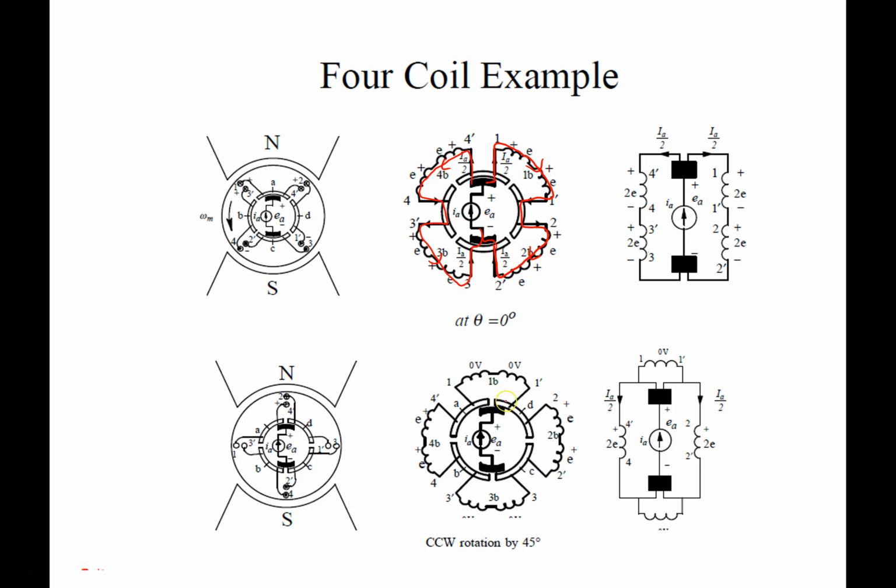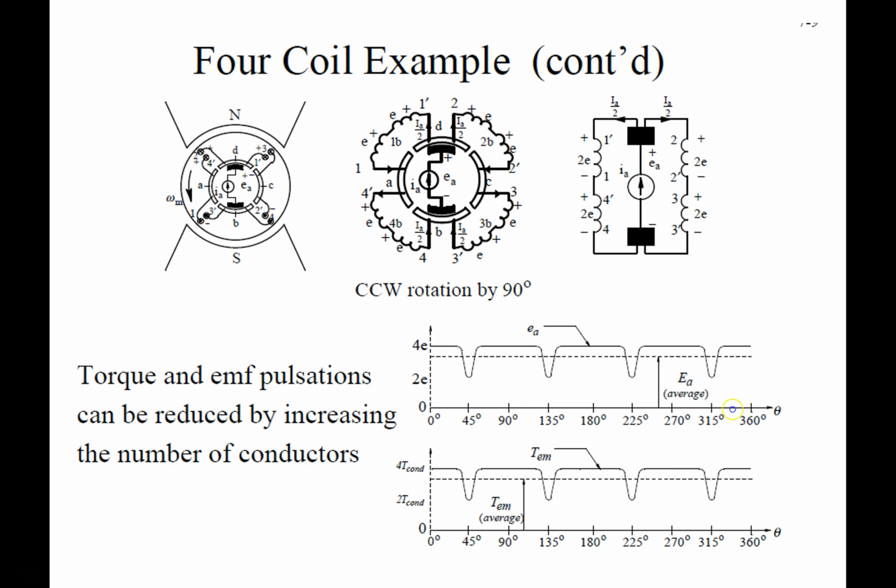Now, when we reach a break in the circuit, what we have is this will become short-circuited, so this winding is not energized. These two are short-circuited, so this winding is not energized, but I still have a break from the top to the bottom. So the current could go like this and like this. So I have two windings being energized while two windings are short-circuited. So in this case, if the windings are all equal, if they're all identical, I should get half torque dip only.